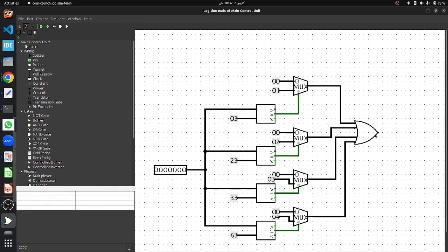Now we are going to use this OR gate output as an input to another mux. Think of it like I'm just using this opcode for the comparator. When the comparator gives me results, I'm going to use this 1, 2, 3, 4, which will act as a select line signal for another mux. So I'm just going to place a multiplexer here, disable this enable first, and connect this with this select line here.